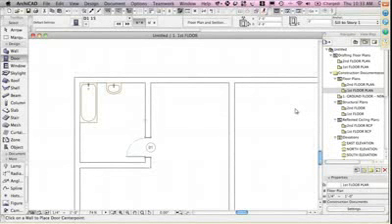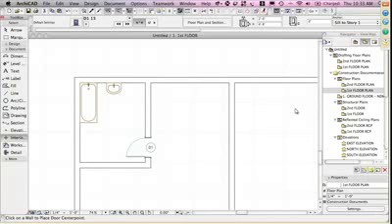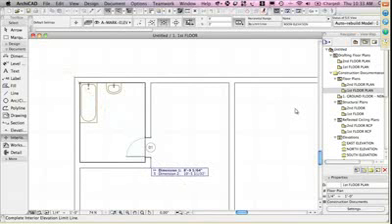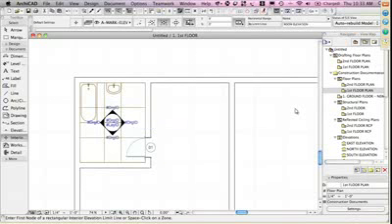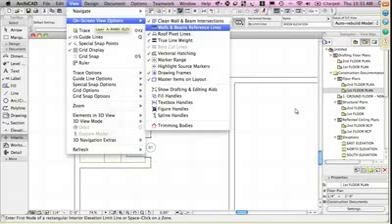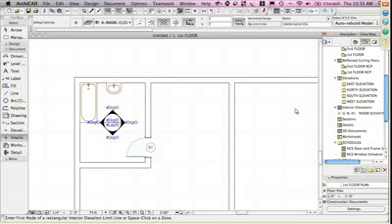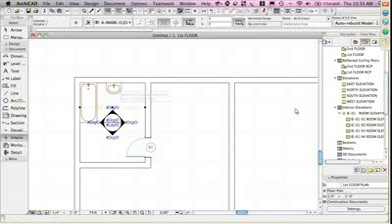And then I'm going to create an interior elevation view. So we'll go to the document menu, put in interior elevations, pick a rectangular array, say I'd like to put in the interior elevations like this, and let's turn off the marker range so that those extra lines disappear. Now I can select this and right click and say open interior elevation. That would be the quickest way.